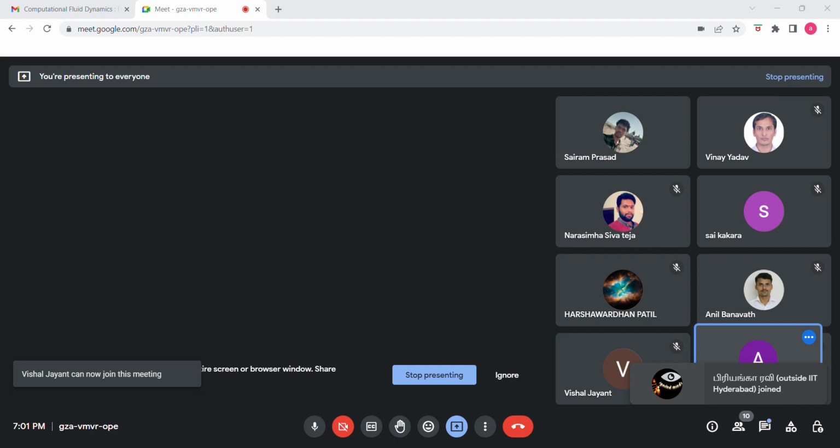It is not always that a finer mesh gives better accuracy. Depending on the system we are solving, the mesh size should be proper. So, more grids will give better results? Not always. It depends on the system that we are solving. And calculation time is directly proportional to number of cells.